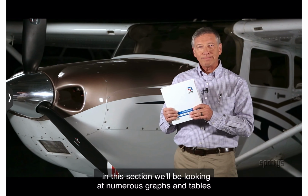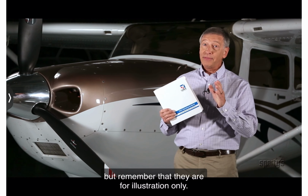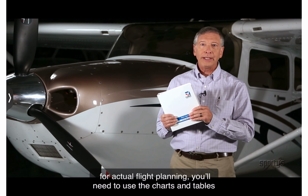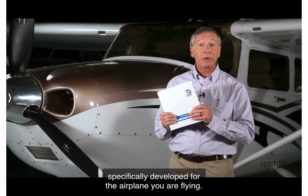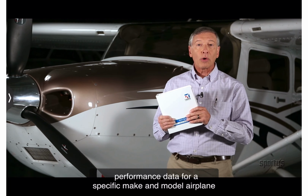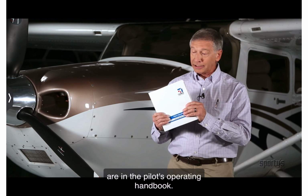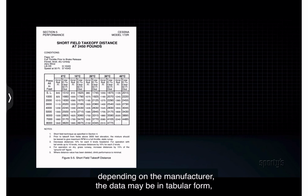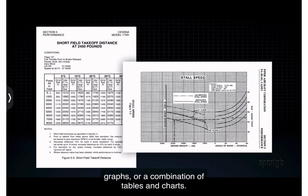In this section, we'll be looking at numerous graphs and tables, but remember, they are for illustration only. For actual flight planning, you'll need to use the charts and tables specifically developed for the airplane you are flying. Performance data for a specific make and model airplane are in the Pilot's Operating Handbook. Depending on the manufacturer, the data may be in tabular form, graphs, or a combination of tables and charts.